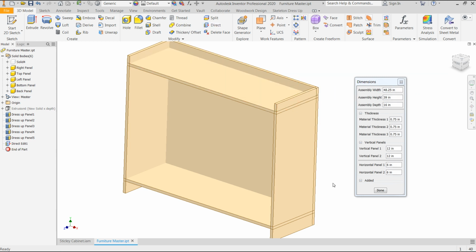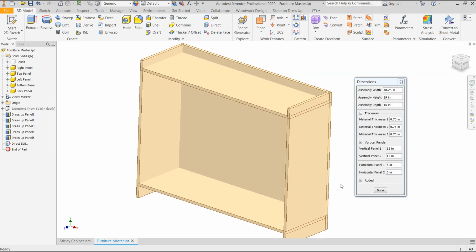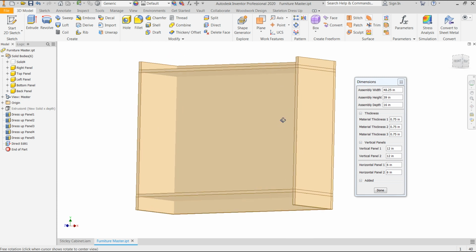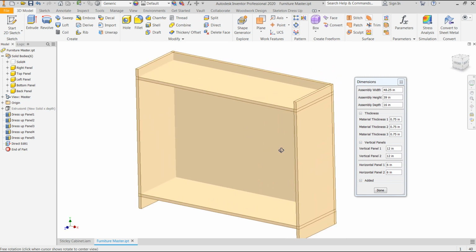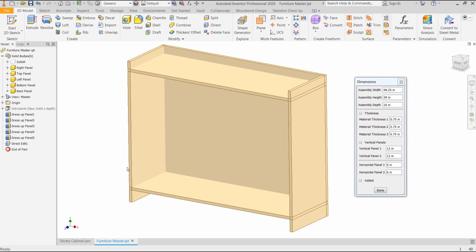Okay, so we have a couple things here that are a little unique. The first thing that we notice is that we have these intersections that can't work. When we're building solid body modeling or using this technique with skeletal modeling, what we try to do is butt everything together first correctly, and after it's butted together and it's accepted and approved, we'll then do the joinery.